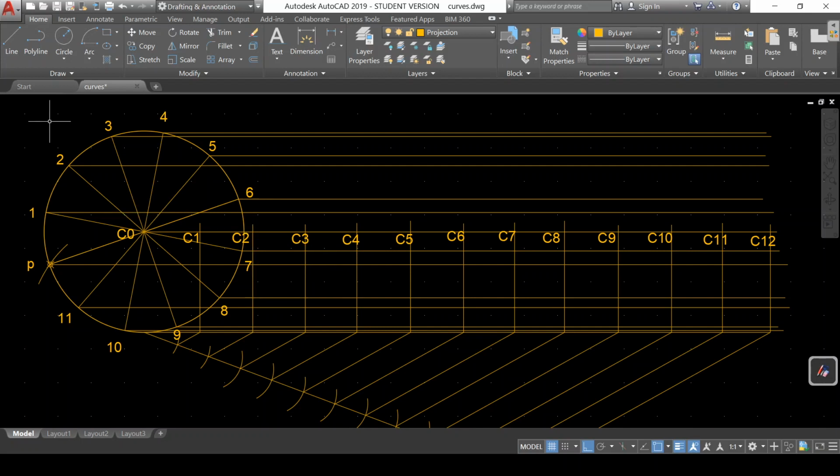Okay, so it is revolving or rolling clockwise. So center will move here. First, after 1/12th, center will come here, C1. So let us take that and draw the arc. So this is the first, and then radius is 30 because this is 60 mm diameter, and let us cut it on the first point locus. Okay, so this is that point P will move from this position to this position after 1/12th revolution.